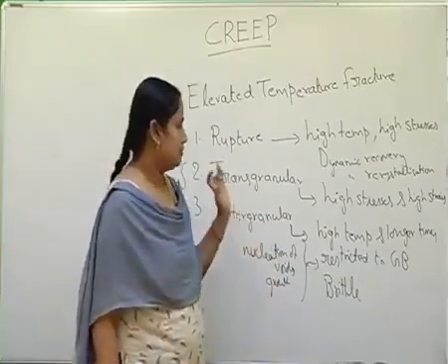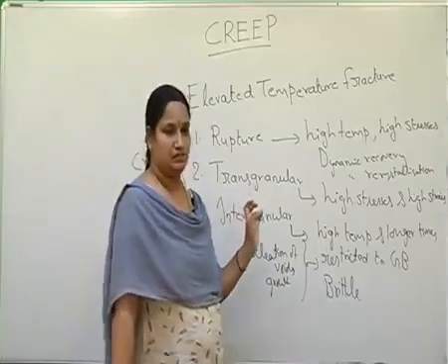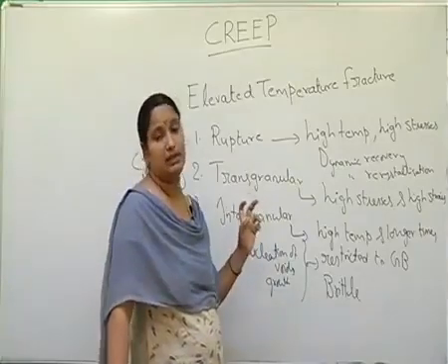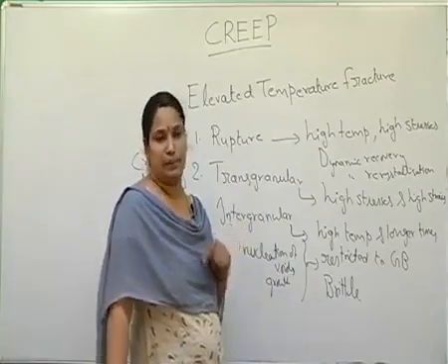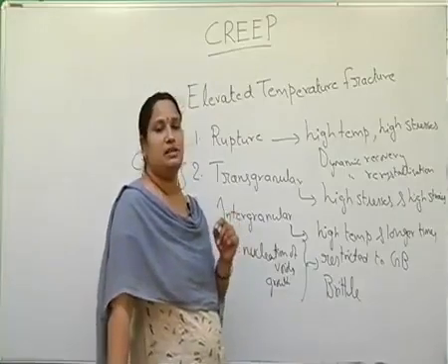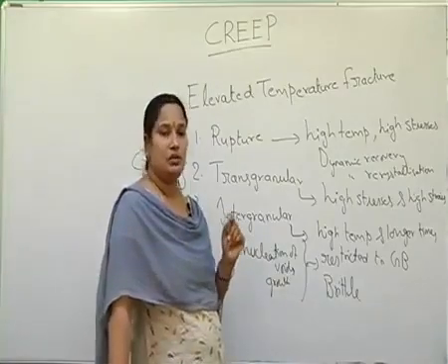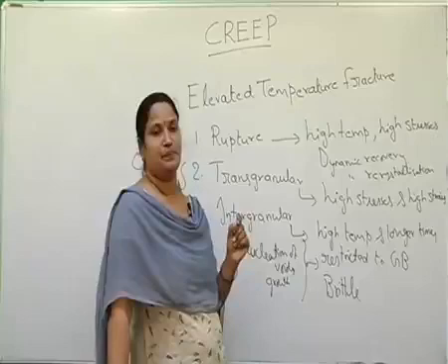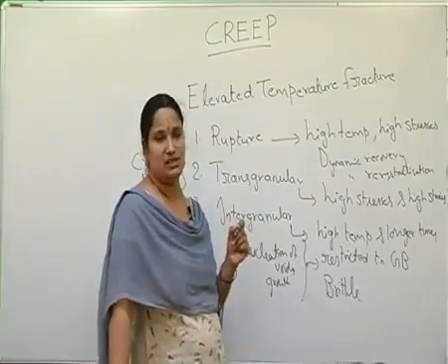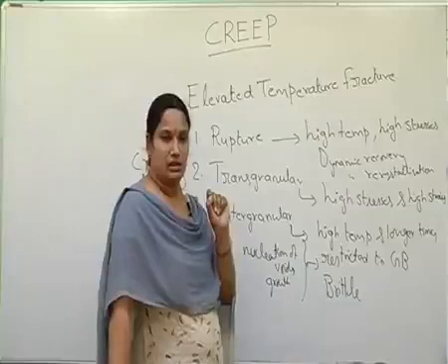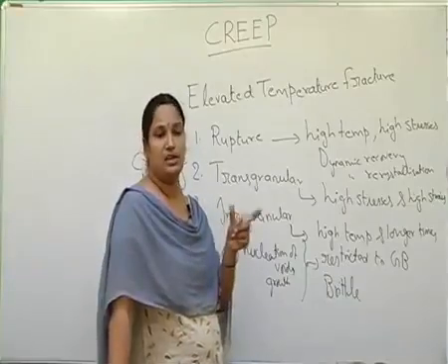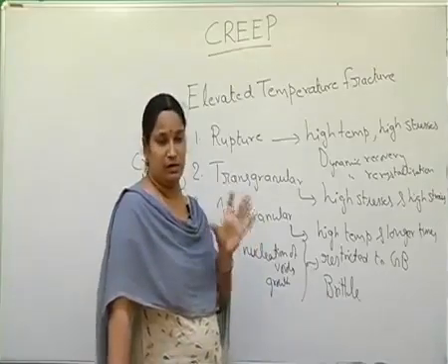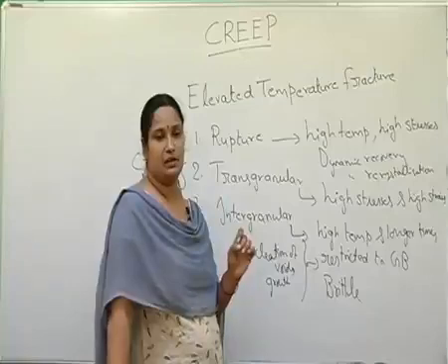And moreover, this transgranular type of fracture is also similar to dimpled fracture or ductile fracture that occurs at room temperature. Because room temperature ductile fracture is also associated with the nucleation of voids, which takes place at stress concentrations, which leads to a triaxial state of stress. At this point, the voids nucleate and grow under the action of the tensile stress. Then finally they undergo a large crack, and finally the material undergoes failure.